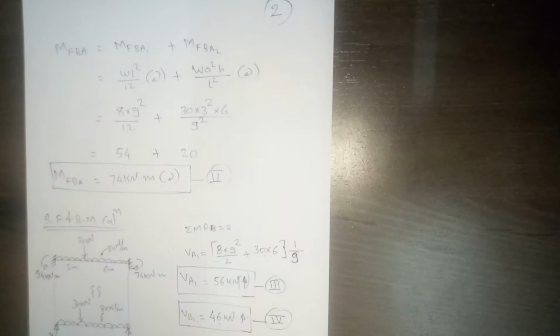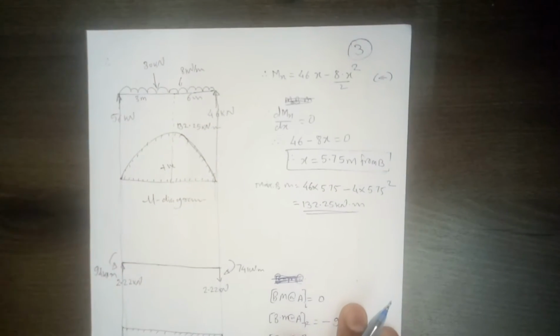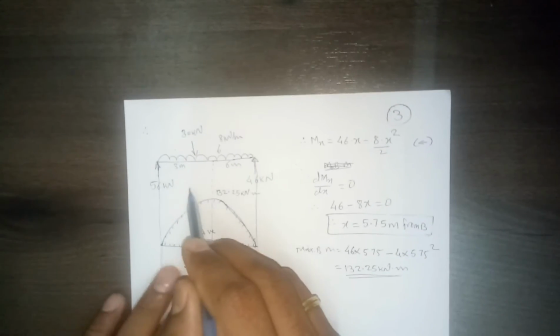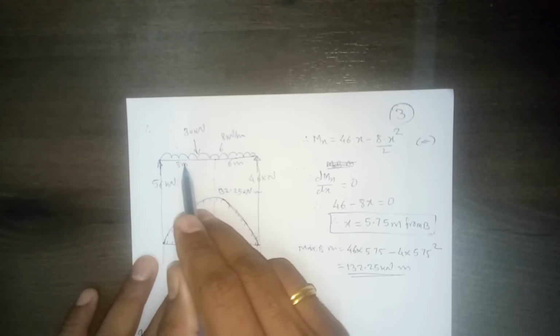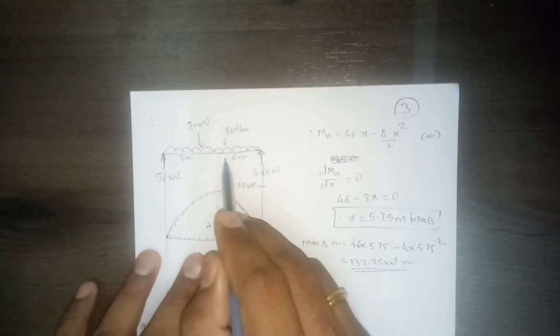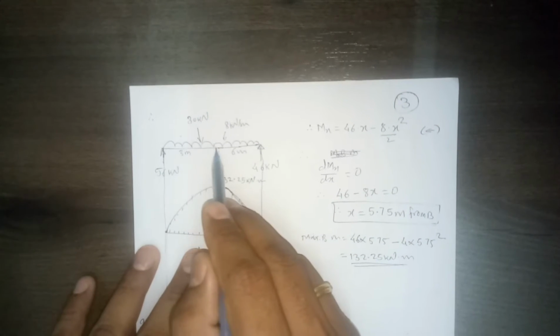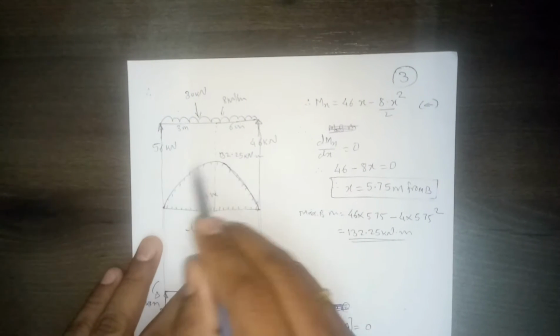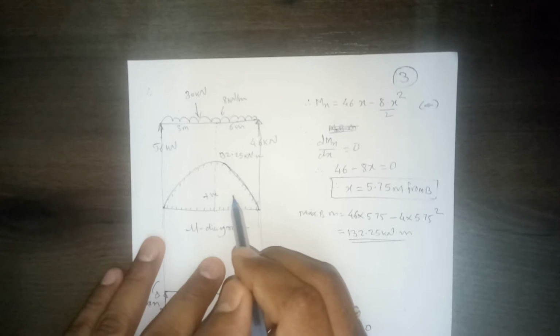But anyway, we are not interested in it immediately. First we'll calculate the bending moment diagram, and then we'll see the remaining part. So now we have to plot the bending moment diagram for this part, this simply supported beam or released beam, for external load. So this bending moment diagram will look like a typical parabola, right?